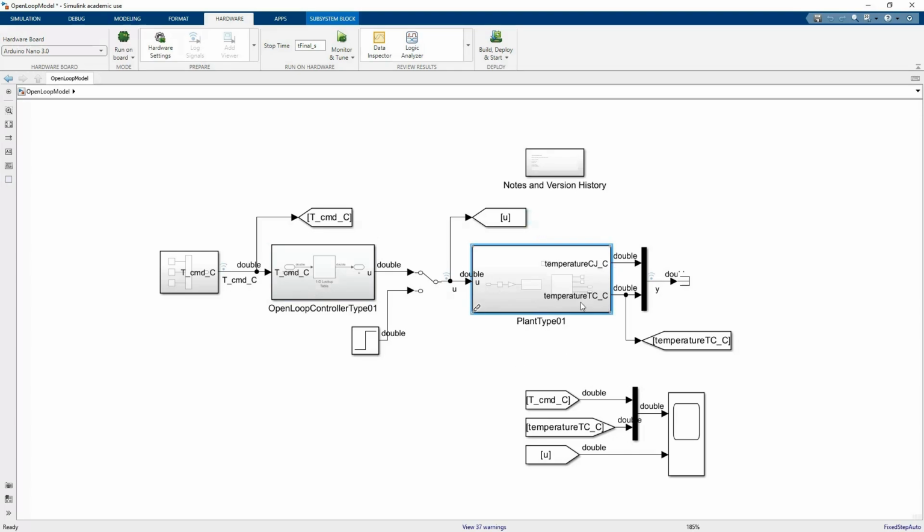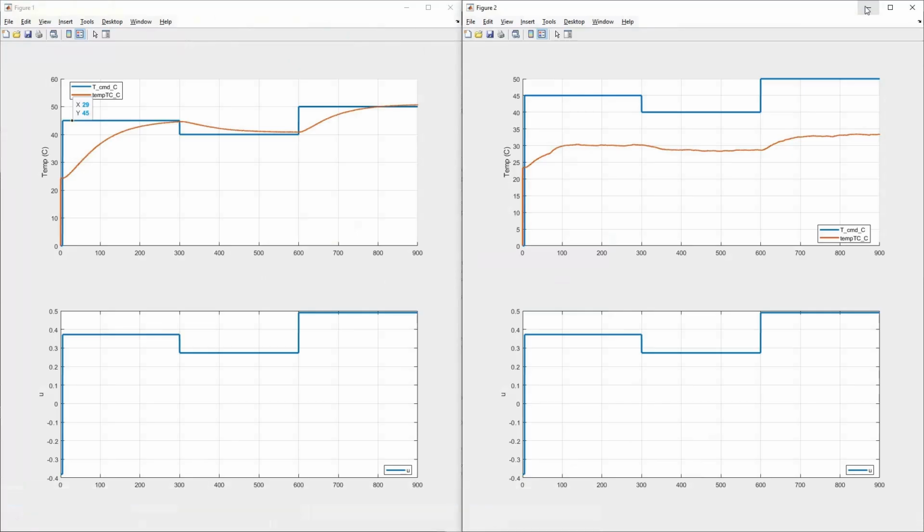So even if there are disturbances that are changing the plant dynamics or affecting something, this open loop controller does the exact same thing every single time. And you can see that by looking at these two traces of the control signal U, they're identical. And now we see the consequence. On the left, when everything was perfect, when the plant was acting nicely, there were no disturbances, this open loop control system did reasonably. But now on the right, when we have the fan on, it's way, way off. It's kind of got the right trends. You can see it heating up, cooling down, heating up, but there is huge steady state error. So again, this is one of the major problems of this type of control system, and maybe we should hop back to the board and talk a little bit more about this.